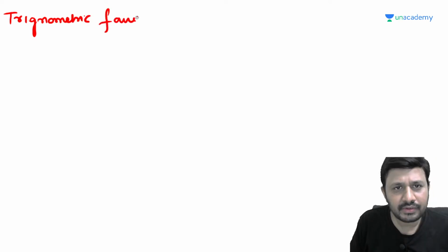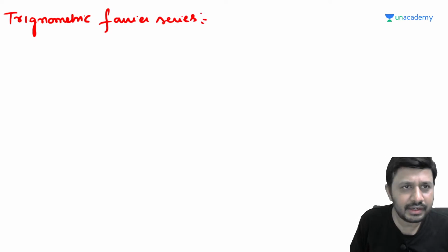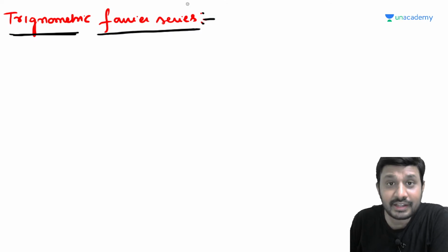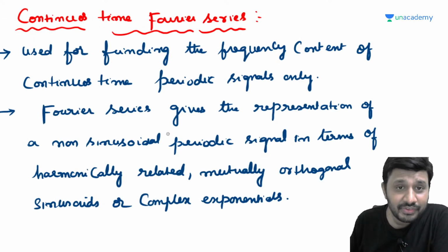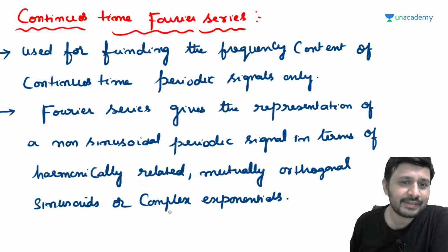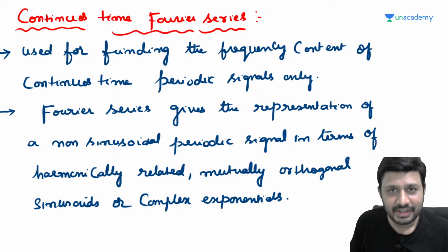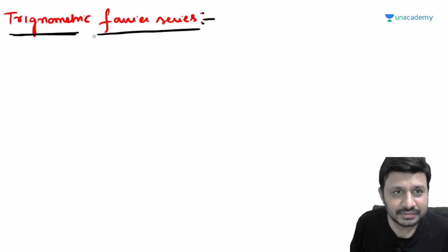See, Fourier series concept, if you want to understand in one statement, we can say that we can build any non-sinusoidal periodic signal using harmonically related, mutually orthogonal sinusoids or complex exponentials. That is the best statement I can give. Let me give the statement.